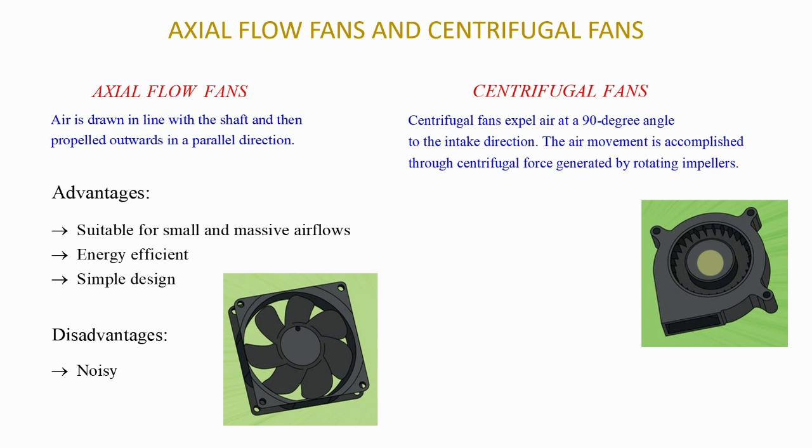Okay, so talking of some of the advantages, when you have a centrifugal fan design for ventilation, it will be possible to operate with high pressure airflow, because a centrifugal fan ventilation system produces high pressure airflow. So in applications where you need high pressure, it might be suitable. Also the structure is robust.